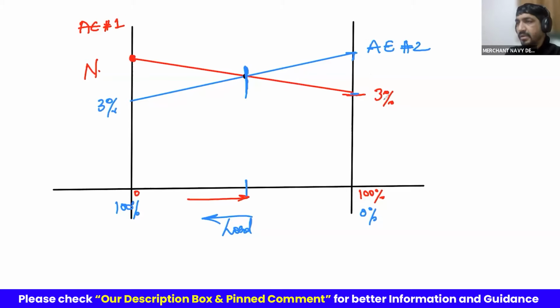All right. Now comes the layman's understanding of why droop is needed to share the load. Well, if the droop is not there, then suddenly the load can be taken up by one generator completely, which may risk another generator suddenly shedding its load, or even going into a reverse power situation. So if we want to explain to the layman how the sharing of load happens, you can explain it this way.